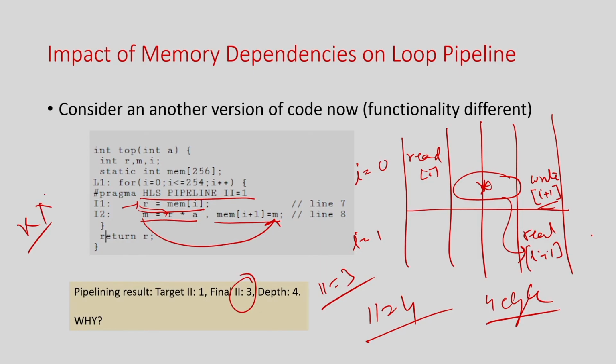In general, if there is no loop-carried dependency, pipelining gives you the best performance. I can execute the loop in order of n time. But because of dependencies, in some cases no pipelining is possible, and if one iteration takes k cycles, it will take k times n. In a pipeline, even if one iteration takes k cycles, I can still execute the loop in n clocks.